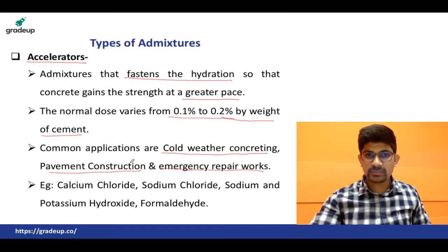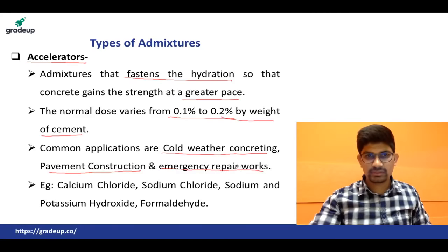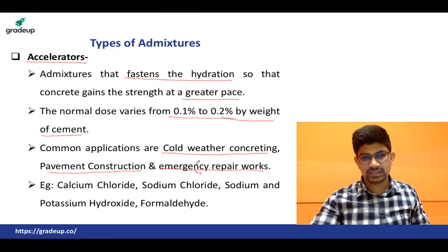Similarly in pavement construction, because you are inhibiting traffic, that's why pavement should attain strength early, so that as soon as possible you are able to release the traffic. Then emergency repair works, for emergencies early strength is required, so accelerators are used in that case also.